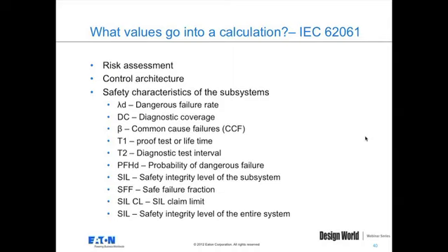So you're looking at your dangerous failure rate, which is similar to an MTTF, a diagnostic coverage, again, similar to the diagnostic coverage in 13849. Common cause of failure, so there are items you have to address to make sure you're not susceptible to a common cause failure. Proof test or lifetime, so how long the machine is designed to be in use, or how long it'll be before it's overhauled, if you will, or all the necessary components are replaced.